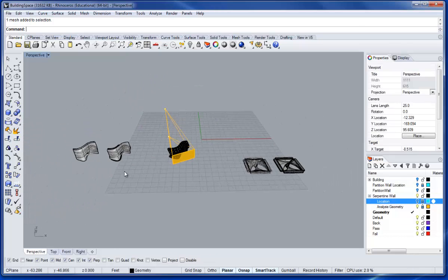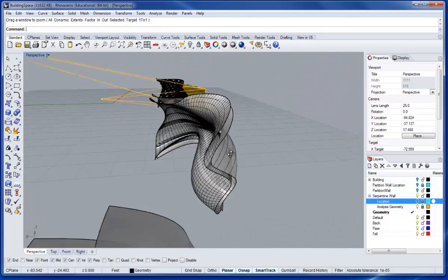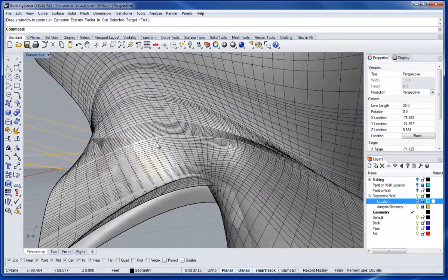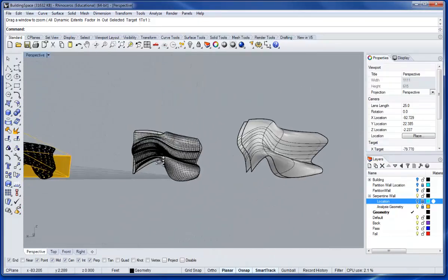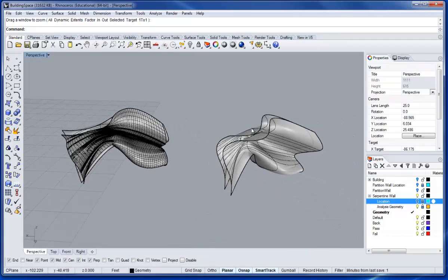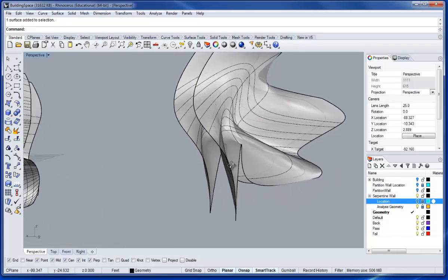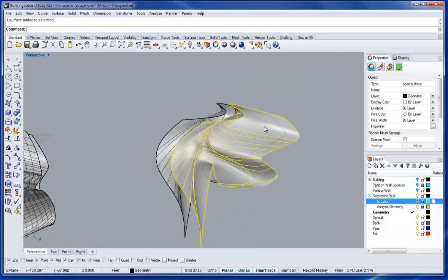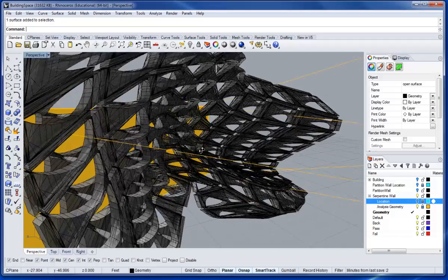I also wanted to highlight a different strategy for generating that secondary surface. What I've directed you to up to this point is offsetting the surface, and you can see that sometimes that generates some complexities. We have a really tight geometry here and some bad geometry down at the bottom. If you're having trouble making that work, instead of offsetting the surface, you can copy the surface a certain distance away along a vector. What I've done is move this 1 foot away to set the thickness using the same surface. So these two are essentially identical, and we'll use those to define the space between. That's what I've done for the generation of this right here.